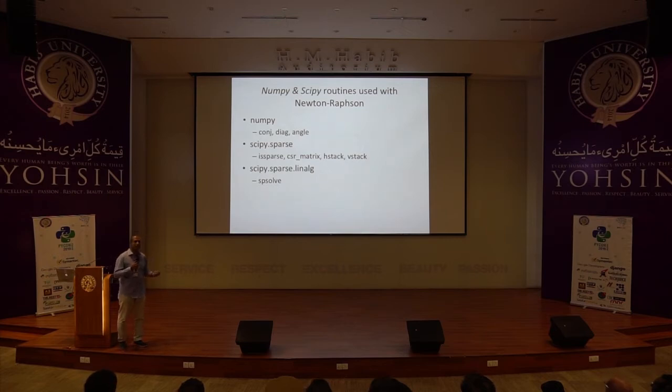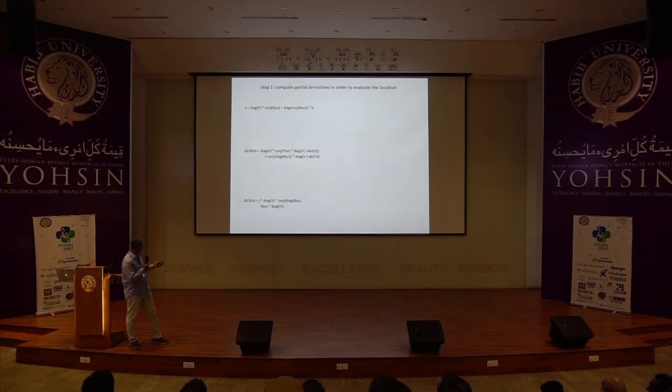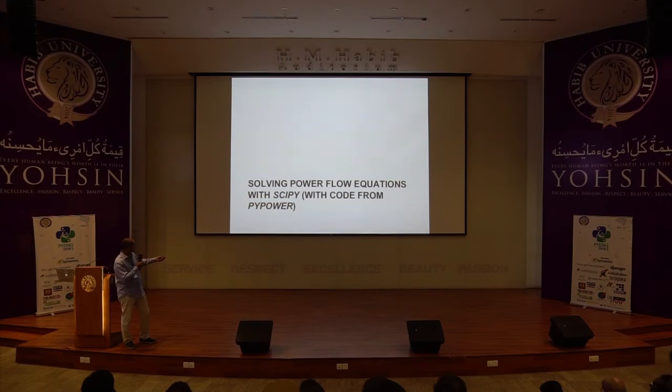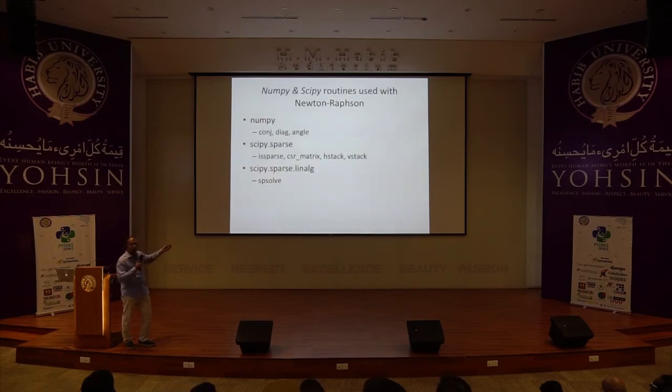Okay, so when you have a system like the power system I'm going to show you very soon, most of the nodes are connected to just one or two other nodes. So if there are like 5,000 nodes, you can imagine that the matrix is very sparse, right? And if you want to solve a matrix equation like this, if you ever try to invert a sparse matrix, the inversion of that matrix is very dense. So you're going to end up with something which is an absolute monster. So you don't want to do that. So you use sparse matrix libraries because they're actually optimized for sparse matrices. Okay?